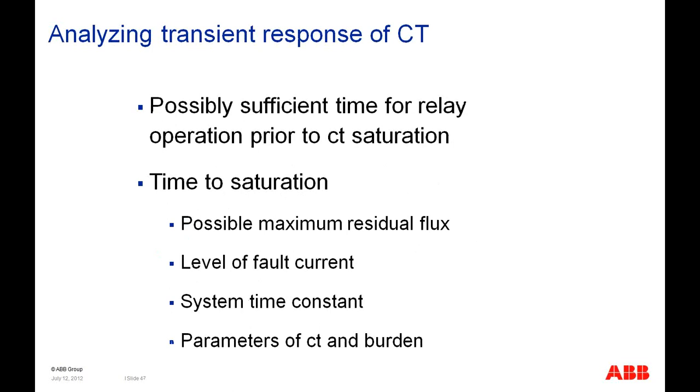One thing nice about a current transformer is that if you throw enough current through it, the current transformer will eventually saturate as you put more and more current through the exciting winding. The one inherent nice thing about saturation is that it doesn't happen immediately. It takes a while for the flux to build up to the point where the CT saturates. So we have this factor known as time to saturation that we can use in our power system studies to determine if the CT will actually perform properly for us in a